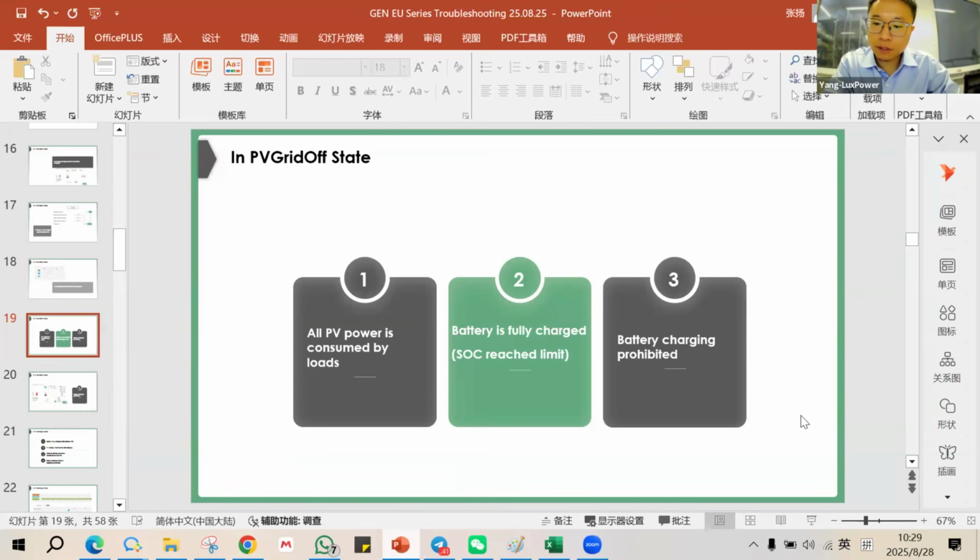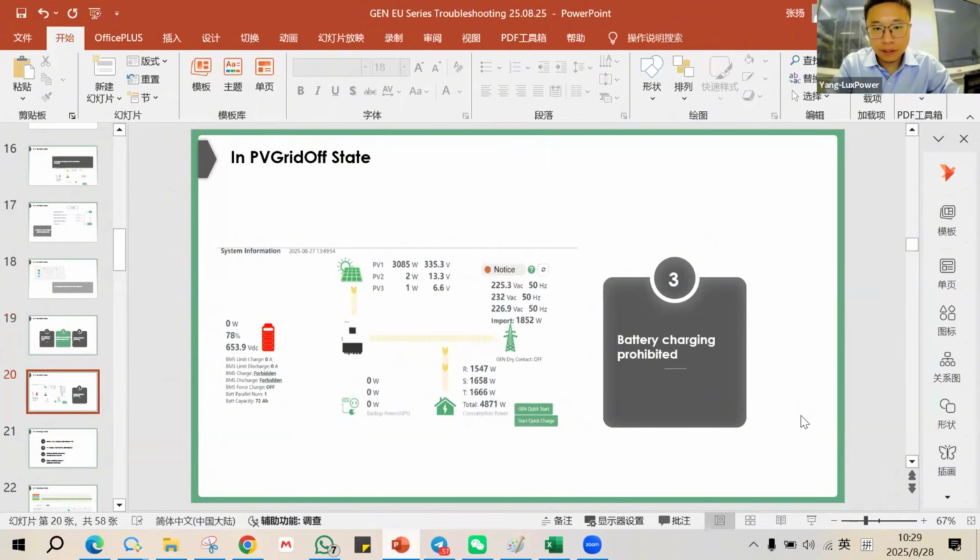If you choose lithium battery back to lead acid mode without communication cables, and in this case the battery works, the battery shows in green in your monitors and charging and discharging work fine, that means the communications between the BMS and the inverter have some problems. But if it still doesn't charge, you need to recheck your battery settings, also make an update from your BMS, or you can contact your BMS manufacturer. And yeah, that's this case.